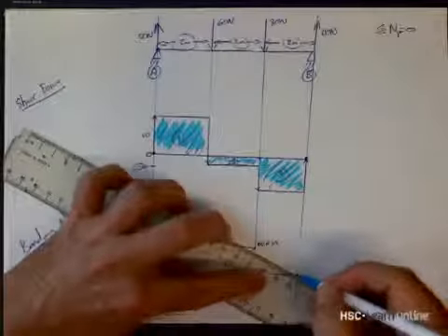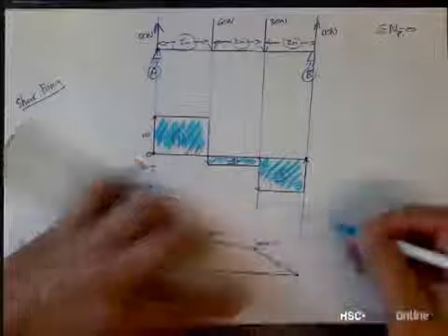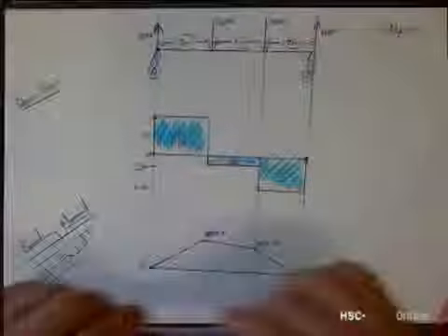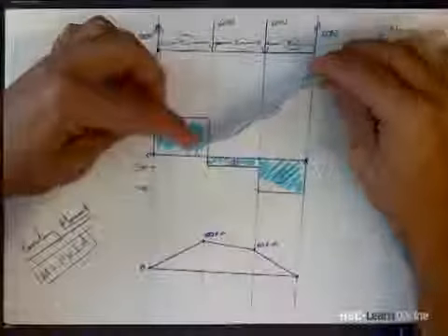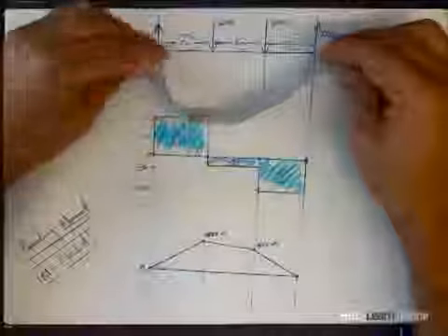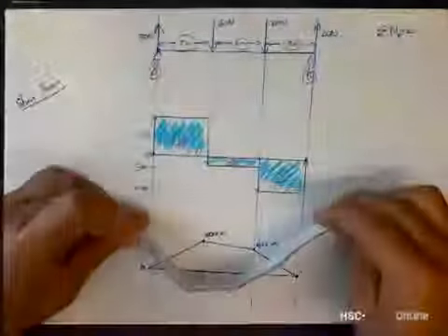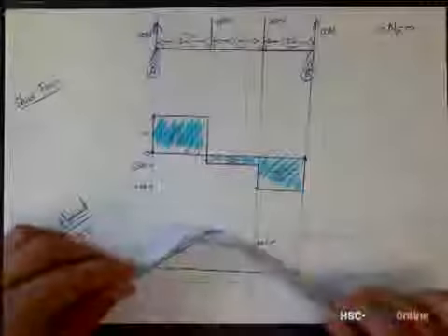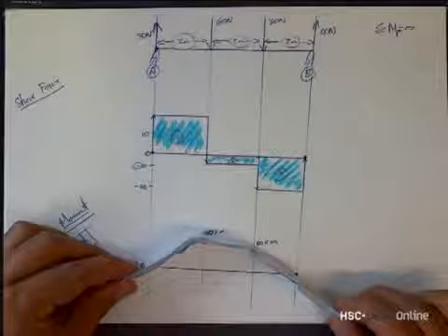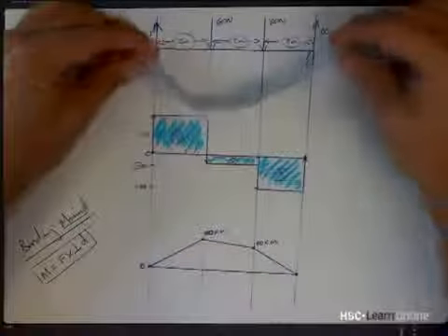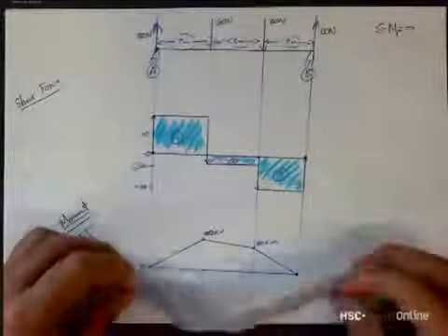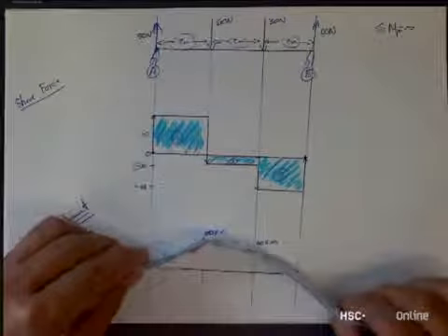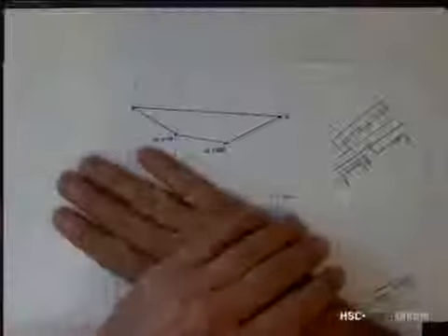And what you should see is an exact opposite or invert of what we said the bridge was going to look like. We said the bridge is going to look like something like this. It's going to bend something like that. And what you see is it's an exact replica or invert of that. So the bridge was going to be bending like that, and when your bending moment's done, it should look exactly upside down. That's what the bridge should look like in a bending moment diagram. So very simply, that's all you need to do.